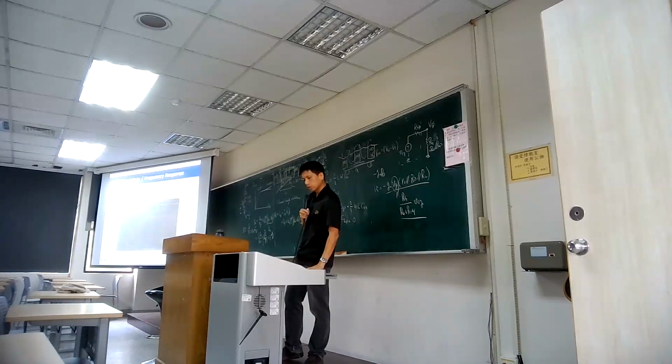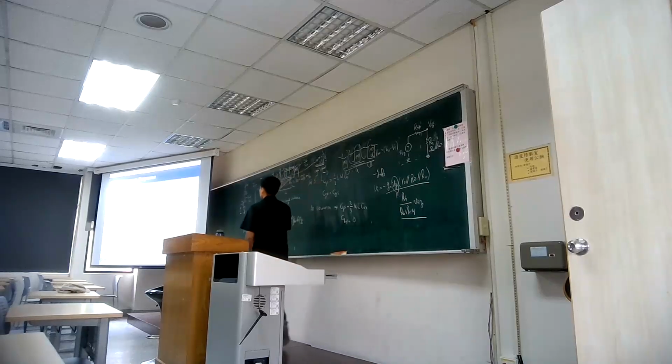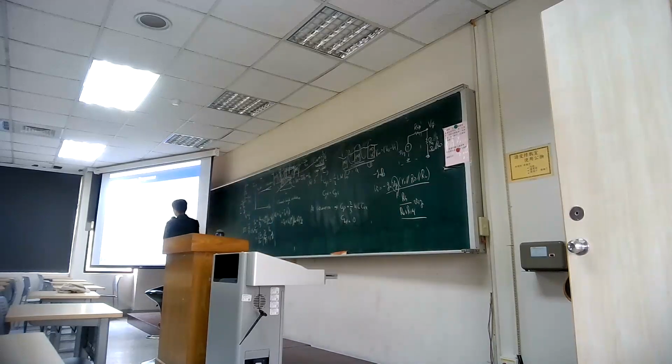We already covered this. I think this one is mostly about circuits and how we improve circuit performance. I don't want to cover that much. So here is the high-frequency response as I mentioned. You can think not only from the transistor itself; there will be a voltage separation between the outside layer. So you can see there will be a CGS and CGD. In the conventional circuit, we didn't have these two parts. As long as the AC frequency is not high enough, we didn't look at the capacitance. But if you work with high frequency, you get an extra CGD and CGS as I mentioned here.